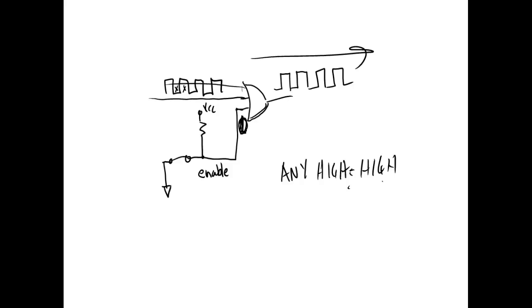But later on, we're going to get into these circuits, and when we look at them, by the way, all combination logic is drawn as rectangles. We're going to see something called E or CS or chip select or something like that, and that's all it is, just an enabled and disabled circuit. And when we start getting into a lot of combination logic, they're not going to draw the individual circuits like we did for the inverter.